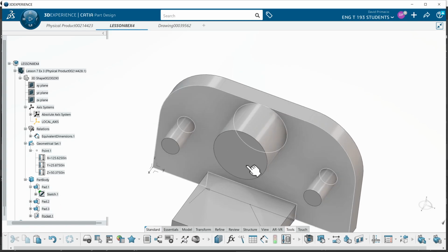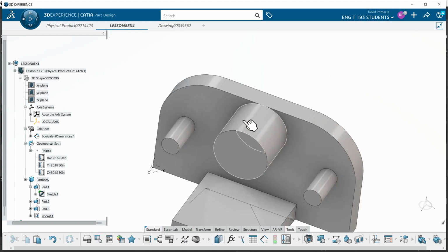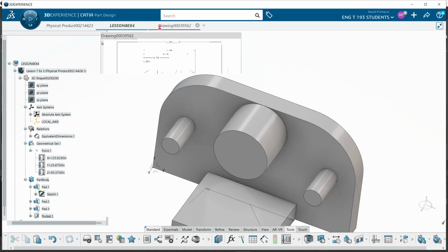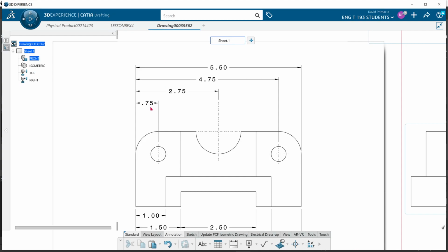Now think of it this way. If they dimension this drawing for this part the same way I'm doing it, technically speaking, on the other part, instead of this one being 7.3, it could be 7.8. And then instead of this one being 4.78, this could be 4.73, which would mean that the pins and the holes would be over 1/10 of an inch off from each other, and they really would not fit. So again,